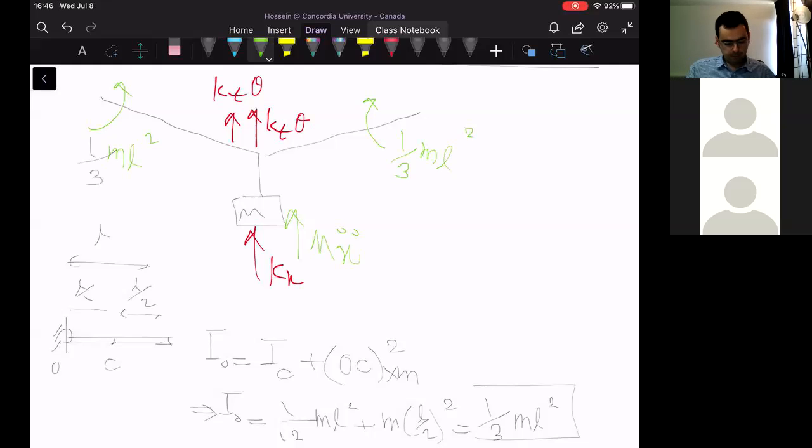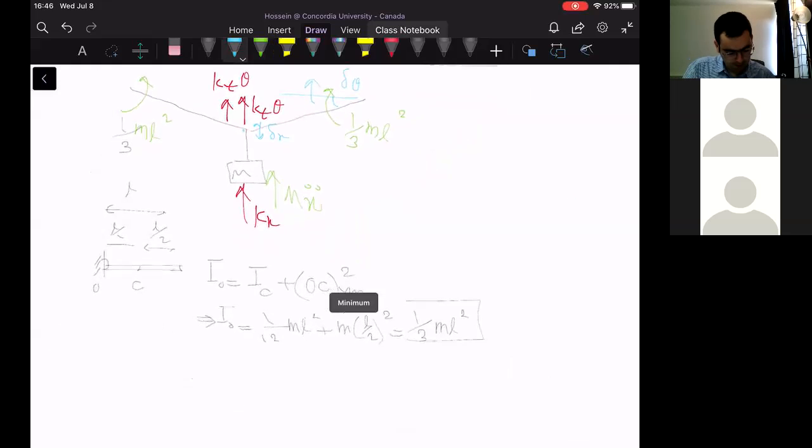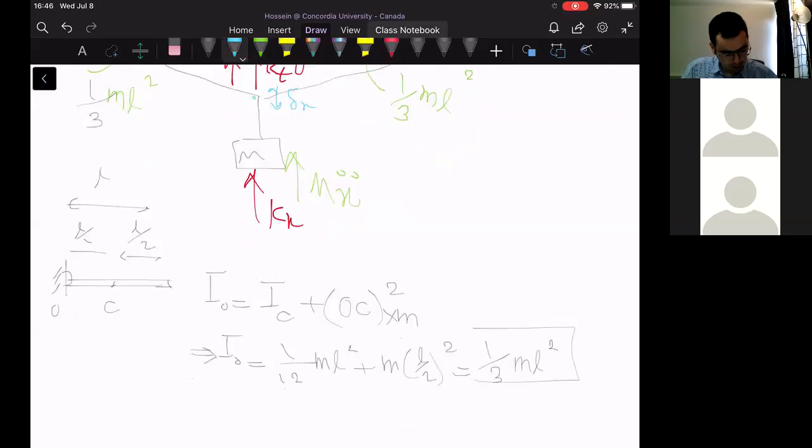So all you have to do is recognize all the forces that oppose the motion by applying a tiny displacement. Now we have to calculate the corresponding work done by each force. There is a small virtual displacement, and also a small virtual rotation, delta theta, which correspond to each other. Taking a look at this figure, we try to write the work done by each force.